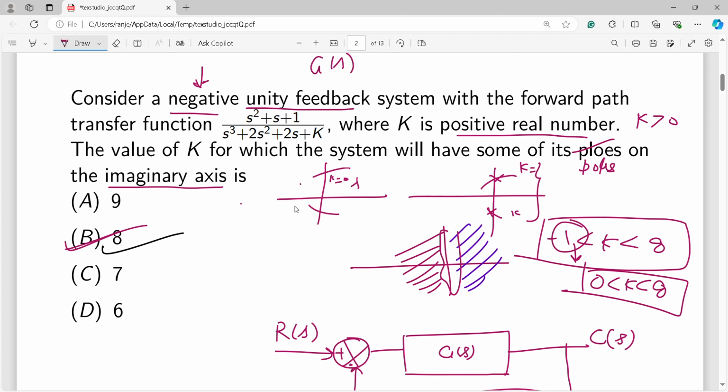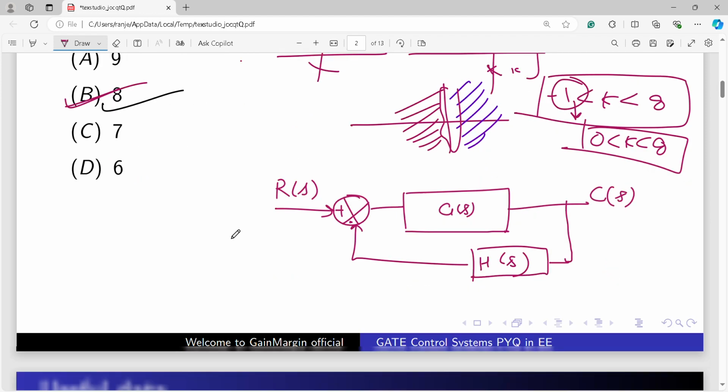Generally, stability related questions are frequently asked. Using the Routh-Hurwitz table, you need not solve for the exact pole locations, but still we can tell how many poles and zeros lie on the left and right of the s-plane, the j omega axis.